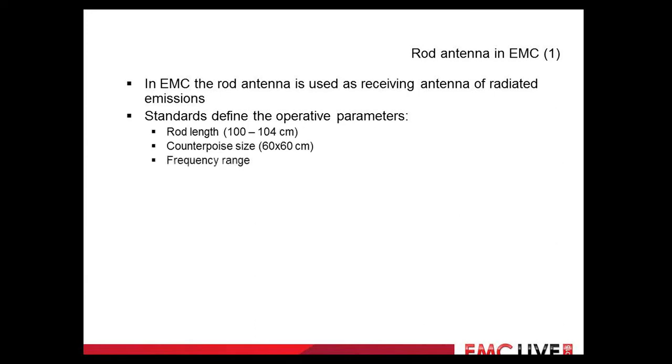The frequency range, usually from a few kilohertz to 30 megahertz, in order to cover the communication bands, low frequency up to short wave. And the field strength range to be measured, so the limits not to be passed, and the detectors to be used in order to read the value of the field strength.